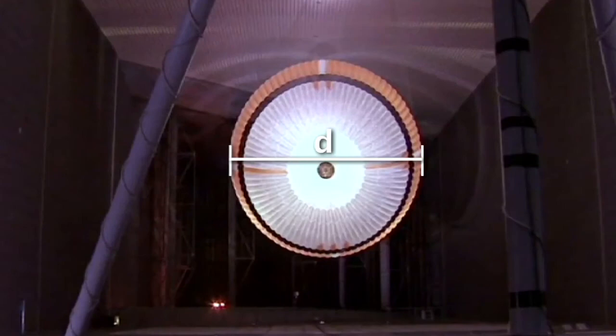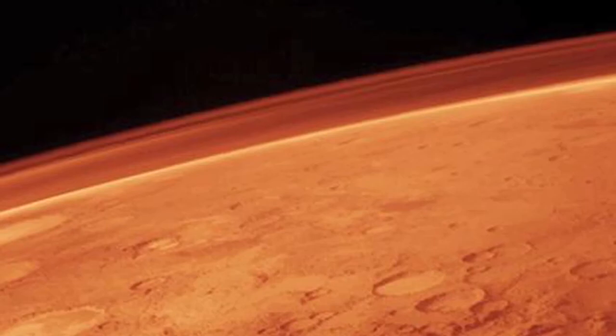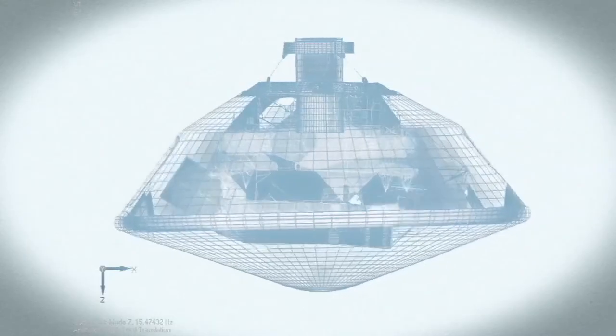In this example, we use dimensional analysis to restrict the possible form of a function describing the terminal velocity of the Mars rover as a function of the parachute canopy diameter, gravitational acceleration, atmospheric density, and the mass of the rover. This allowed us to design a parachute for use on Mars based on Earth-bound experiments.